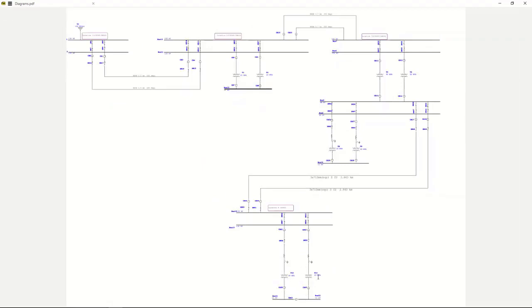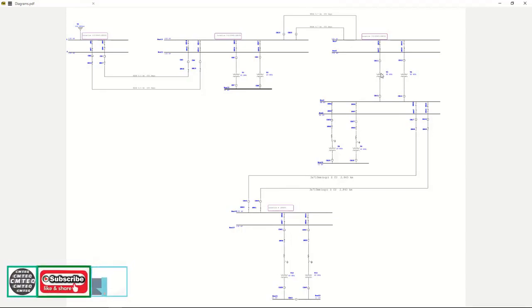Now you can provide a protection system, a downstream protection system that will be all the way up to the power system connection. Remember, if you use IDMT relays, you have to set up your discrimination so that for every circuit breaker and IDMT used along all these bus bars, the total time must not be more than 2 seconds, because otherwise that will be too much to allow a short circuit current to last. It's going to destroy the power system.